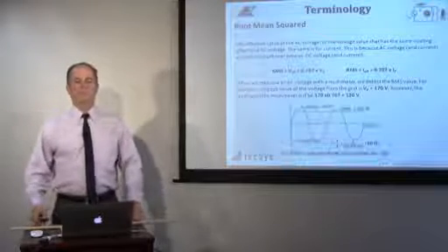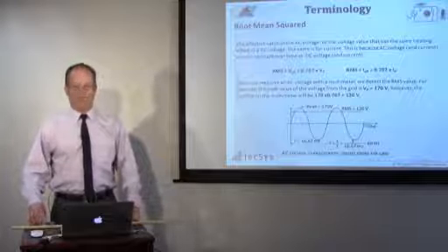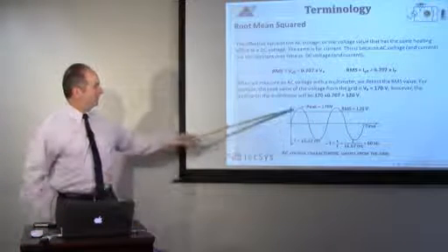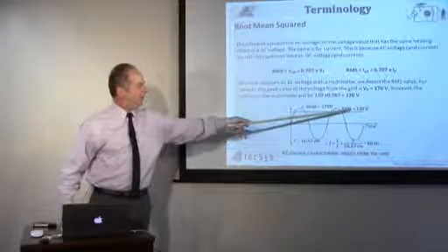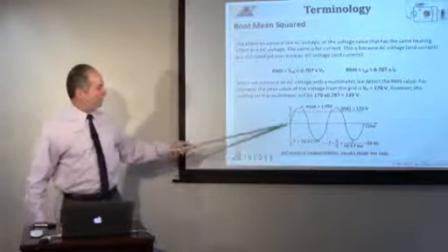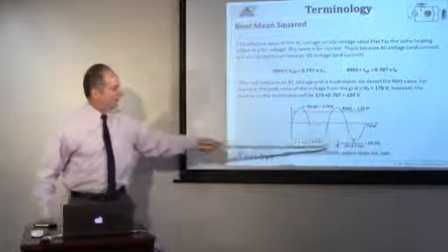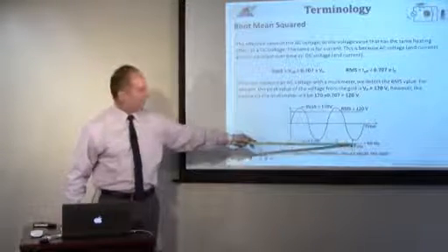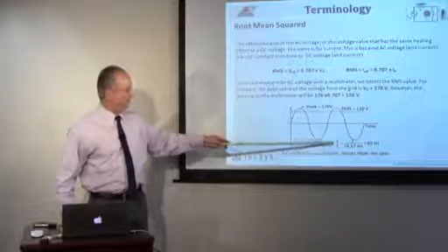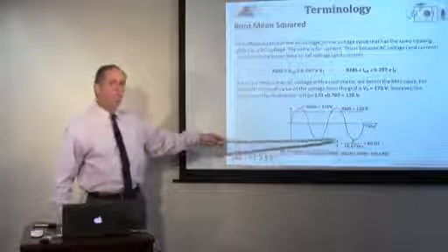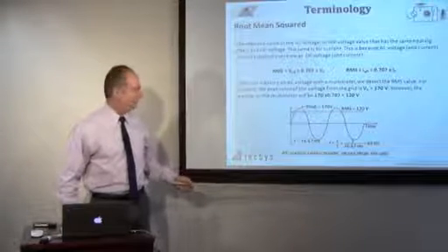Okay, now when we look at the graph of something like this, we have the peak voltage up on the top showing that we have 170 volts peak, okay? We have an RMS value, which is 120 volts. We have a frequency of, we're looking here, 2 cycles, and if we were to choose a frequency of 60 hertz, or 60 cycles per second, if there are 60 cycles in a second, each cycle is 16.67 milliseconds long. Okay?